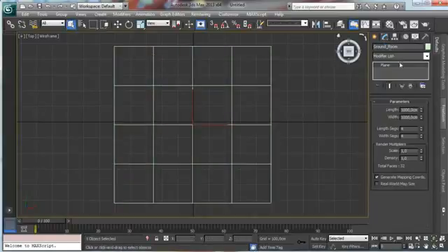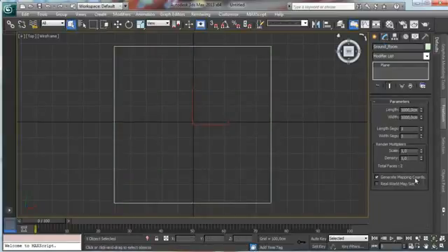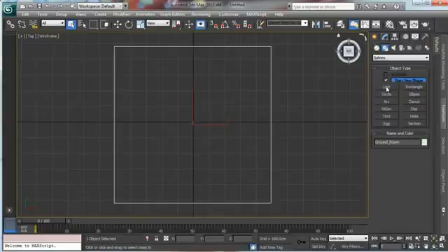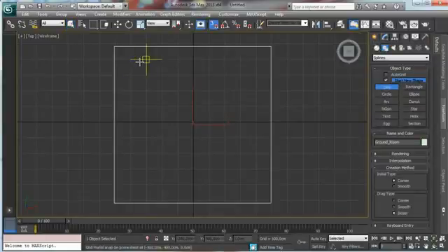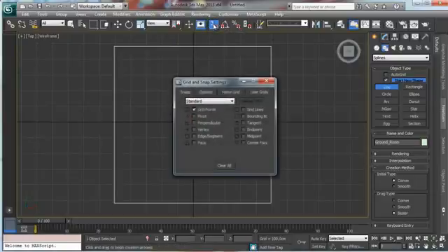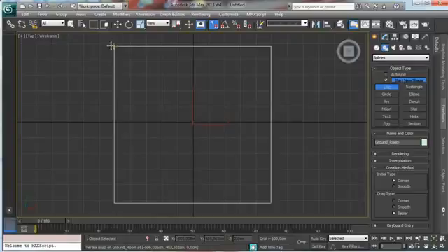But before, I'd like to remove the face there. Then back to the line, S key to have the snap, then right mouse button over the snap, and we can remove the grid points and go for the vertices. So you see that now the snap is to the vertices there.